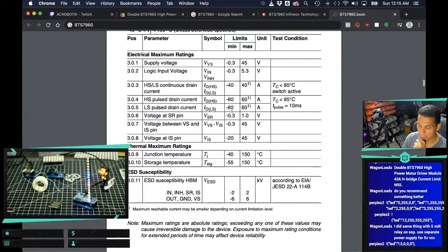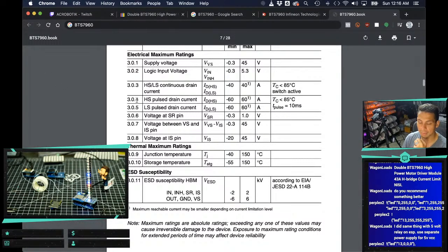So I would just try it without and just power the low side with 3.3 volts, so that the supply on the low side matches the voltage of the signals. And if that doesn't work, then shift everything up, put the 5 volts from your ESP8266 board to 5 volts, and then shift up the signals. So anyway,